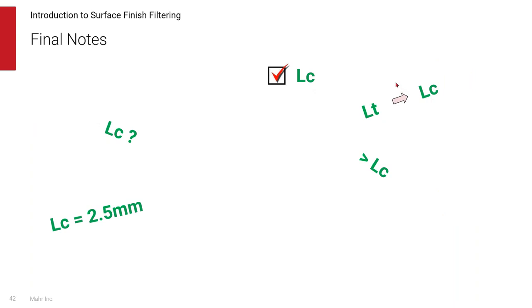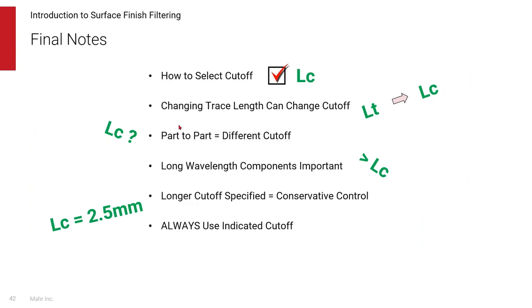You know, there are lots of different parameters with surface finish. We've got our filtering, we've got the length of trace. But what we tried to do today is cover a little bit about what the surface profile is. By using different cutoffs, we can filter out the waviness parts of the profile and just leave us with the roughness parameters.